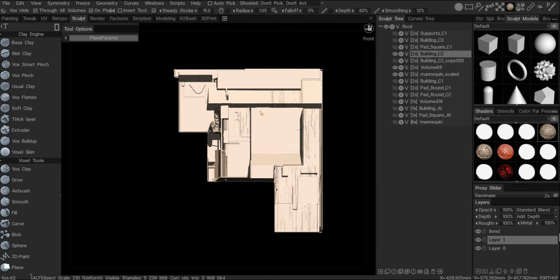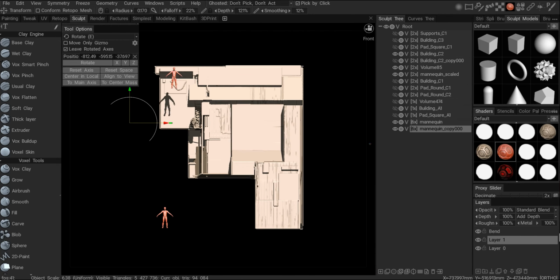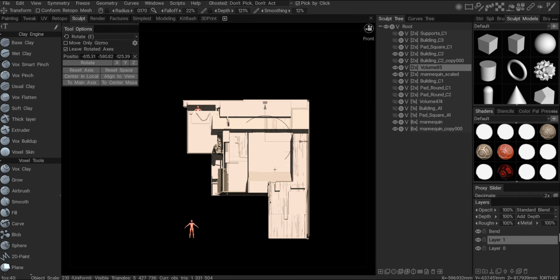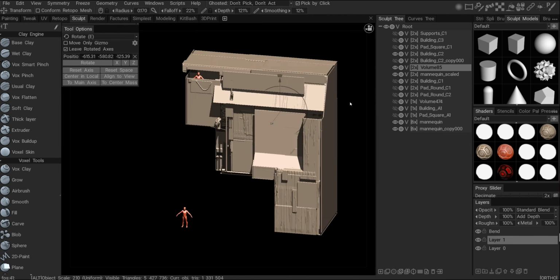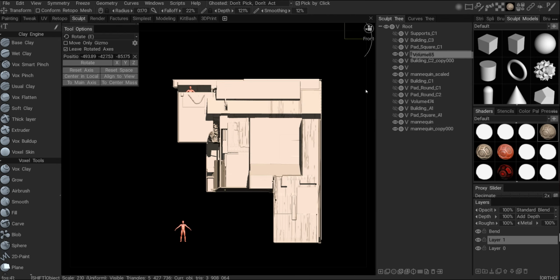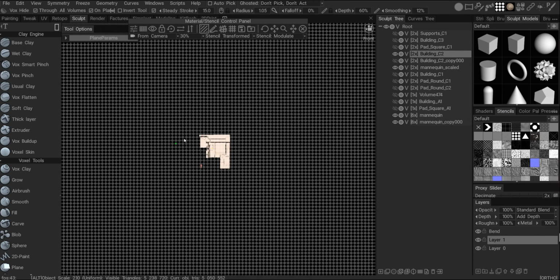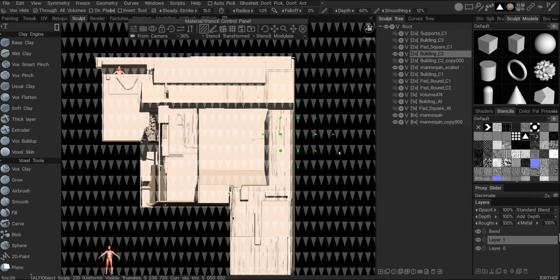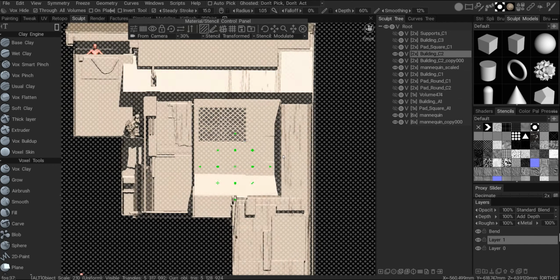The stuff you see in ZBrush, you don't really see in a render in Maya, Unreal, or anywhere, because ZBrush tends to show you more details, while 3D Coat is a bit more true to the point. You can use matcap materials that are almost identical to ZBrush, but I try not to use them too much because they give me a fake sense of details.